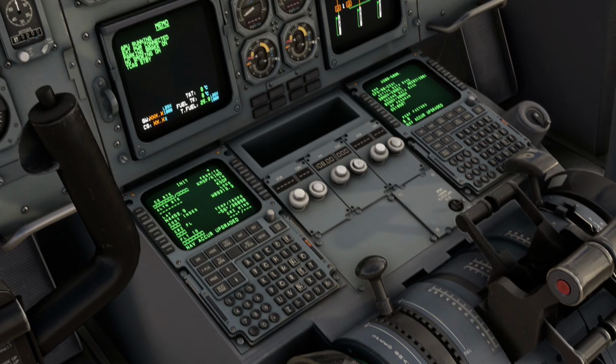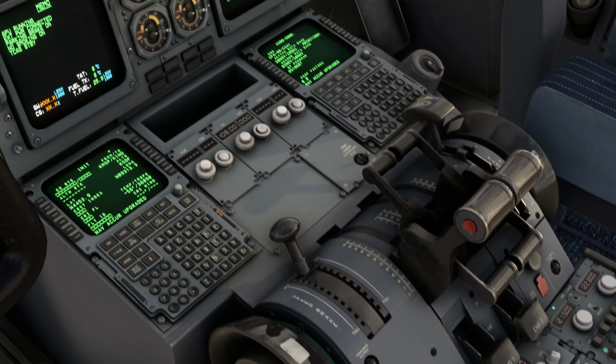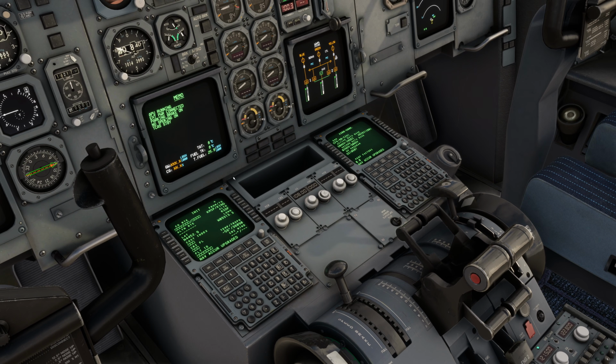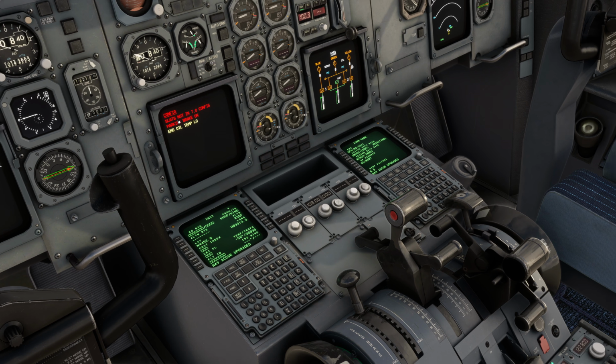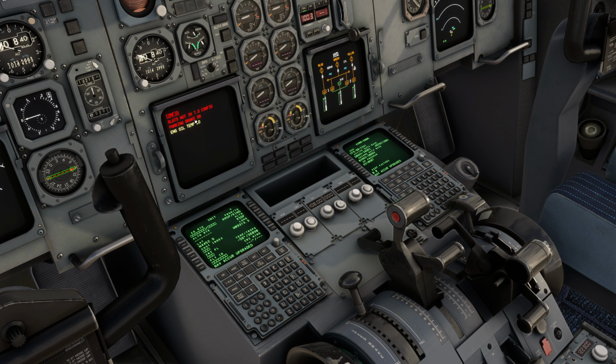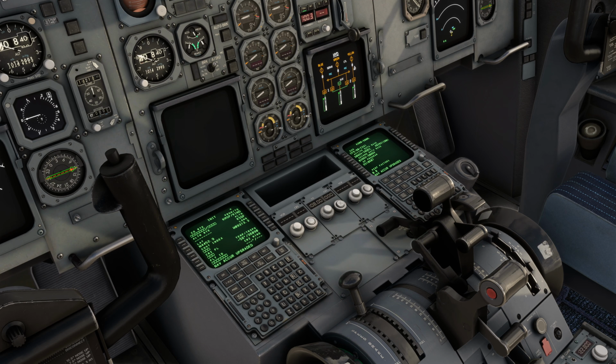Alright, that leads us down to the pedestal. Over here we make sure that the speed brake is retracted and disarmed. We are going to check the takeoff warning system, and that can be done quite easily. We're going to advance thrust lever number 1. And now the config warning system detects slats are not in takeoff config, the parking brake is on, and the engine oil temp is low, so it tells us exactly why we are not supposed to take off. Okay. Return the thrust lever to idle, and then we can repeat the same with thrust lever number 2 to make sure that the sensor is actually working on both